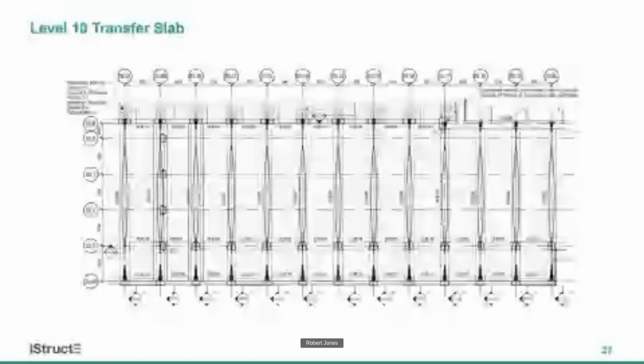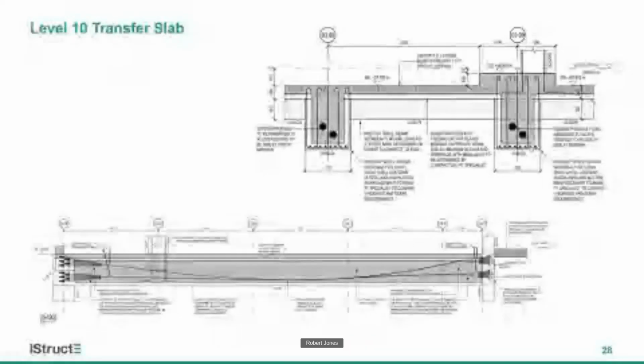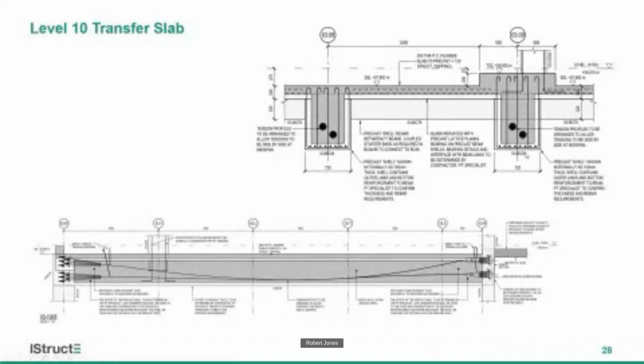What we ended up doing is this sort of shell beam, similar to the bridge construction that Christian was talking about, having a shell beam with an in situ stitch portion in the middle of that with tendons running through there, and a precast block on the end to get the interface with all of the connecting elements, the edge beams and the columns coming up and down through that interface.